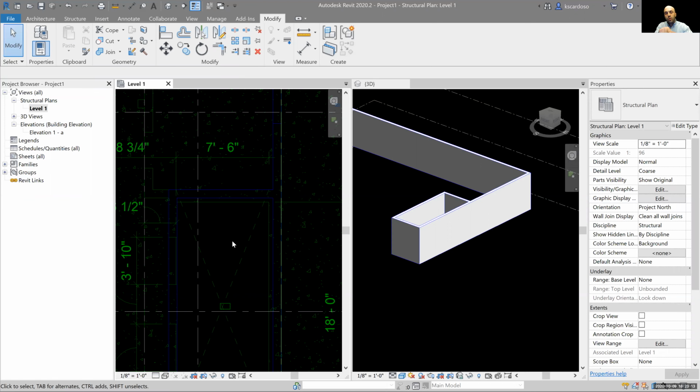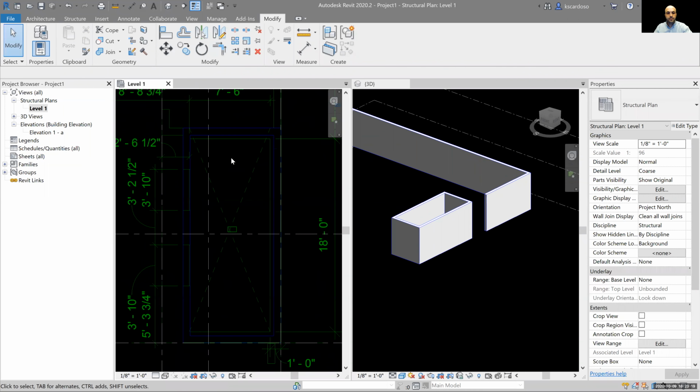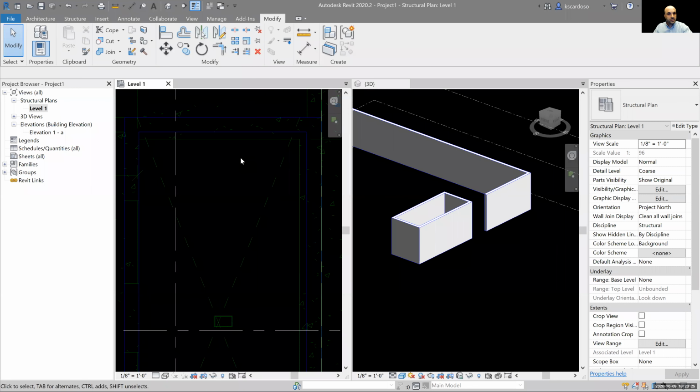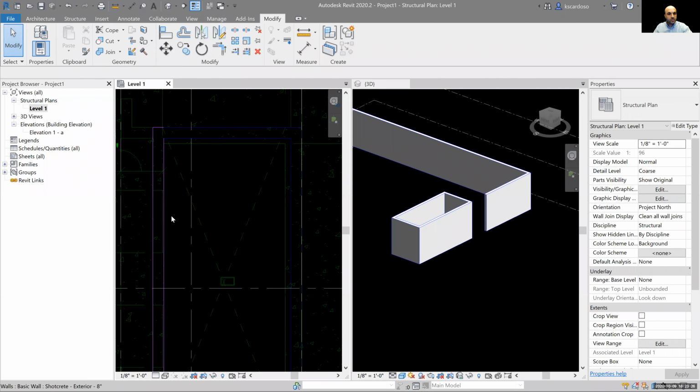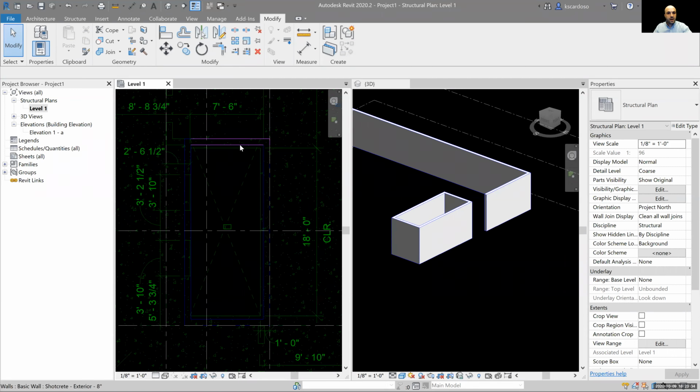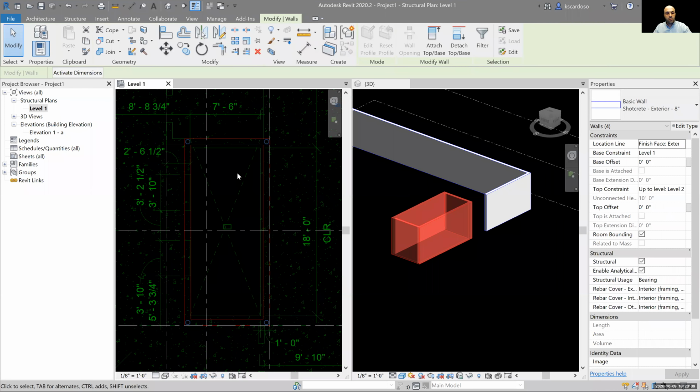And now let's trim that corner of that elevator together. TR and select both walls that you want to keep. Now 3 of these walls are actually 12 inches. You can see that. It's only the walls at where the elevator doors are that is 8. So let's go ahead and select, let's do a hover, tab, click. And now on your keyboard, if you press Control, you can see my cursor changes. It's a little plus mark there. If you press Shift, it's a minus. So let me just hit minus. I don't need those 3. And now you can update your walls.